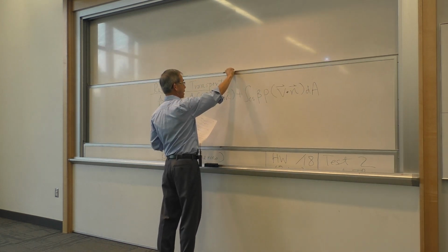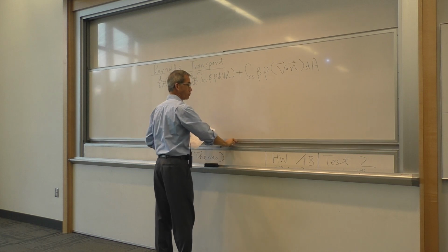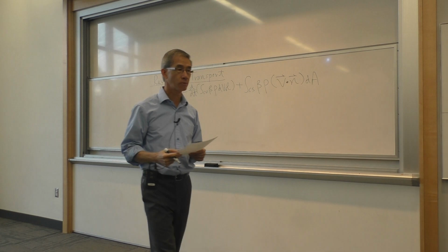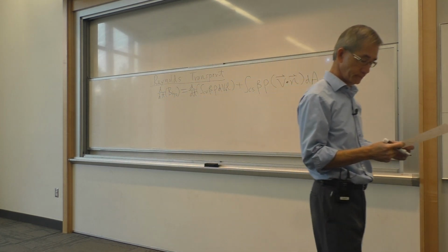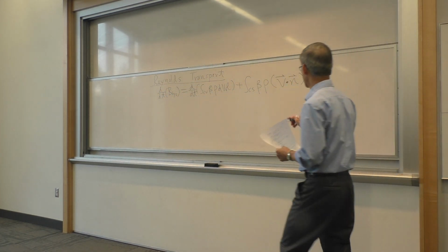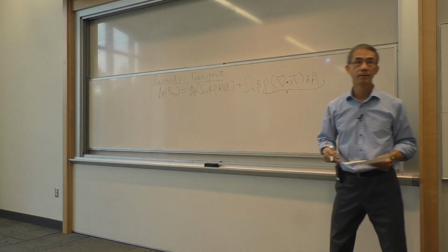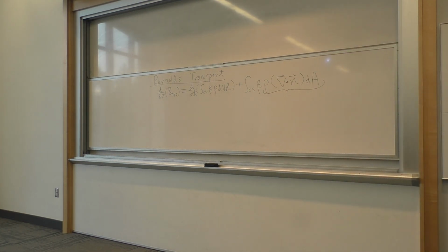So this is a general transport theorem due to Reynolds, which allows us to take a system equation and make it into a control volume application. Can someone remind me what this somewhat intimidating integral over a differential area, with the density and a dot product of V dot N, really means?